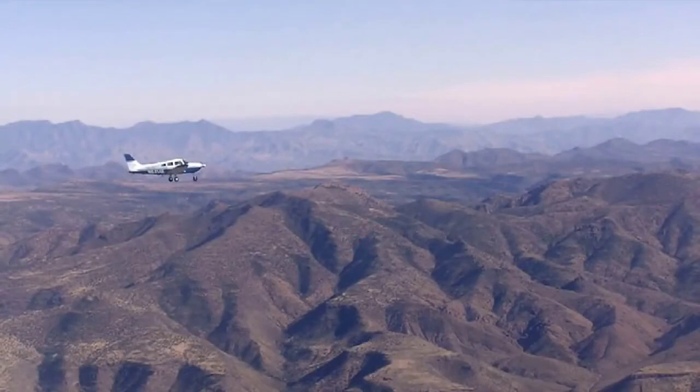In the United States, for instance, transition altitude is 18,000 feet. It makes sense for the US to use such a high figure. In general, it is a good idea to be on QNH when in the vicinity of high ground. There are peaks well over 14,000 feet in California and the Rockies, and over 20,000 feet in Alaska.